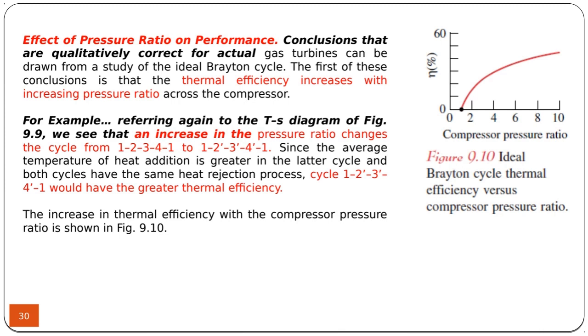So in the internal combustion engines, remember that by changing the compression ratio, the ratio of the volumes, it's possible to increase the efficiency, but there are some limits to it. For instance, for gasoline engines, the limit is auto ignition or knocking phenomena.